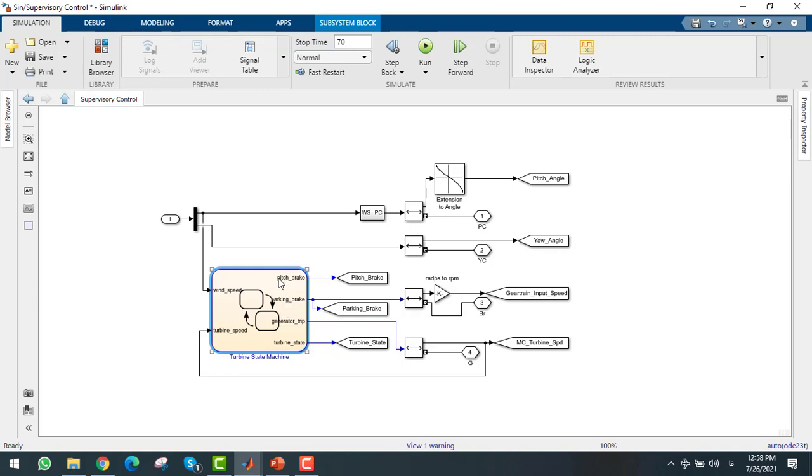For example, if the wind acting on the blades touches an upper limit value, a pitch brake command will be generated, causing the blades to position themselves so that there is the most drag and less lift generated on them. After that, the brake system will be engaged, stopping the turbine at once.